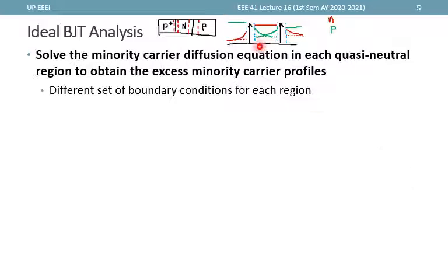However, these two trends individually will only happen if the carriers die down to around 0 excess carrier concentration, which only happens when this region is long enough. But the BJT is designed such that only few carriers will recombine, and so what we will actually get is some plot like this for the case that both junctions are forward biased.